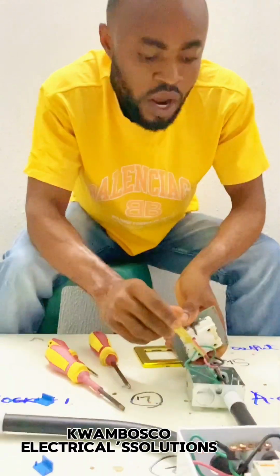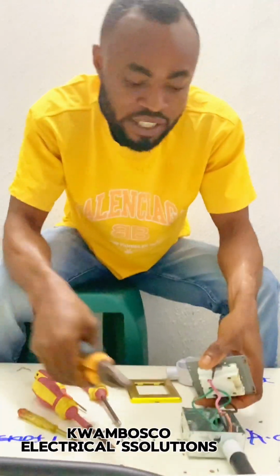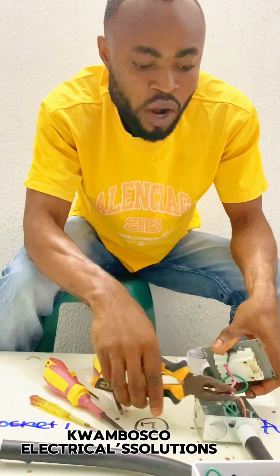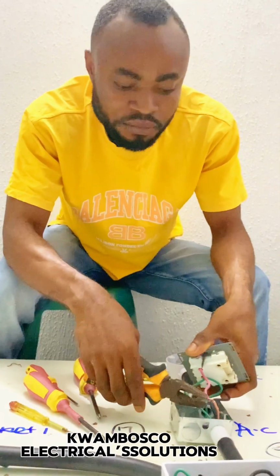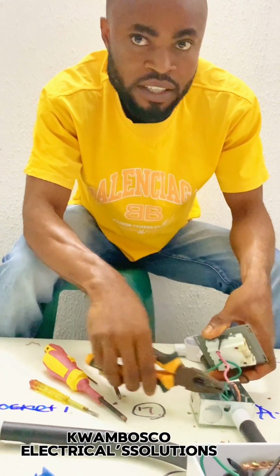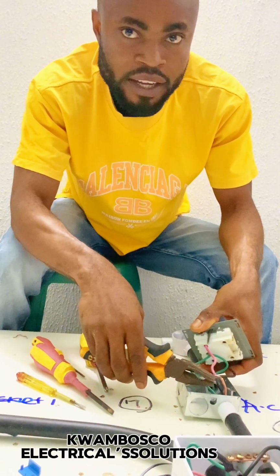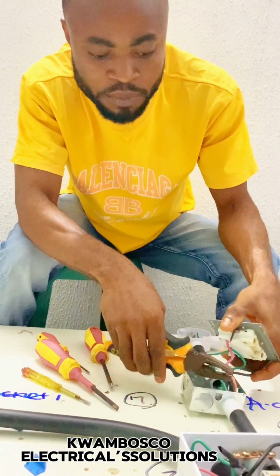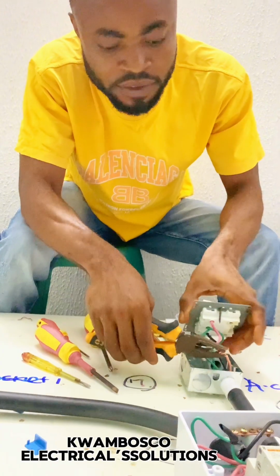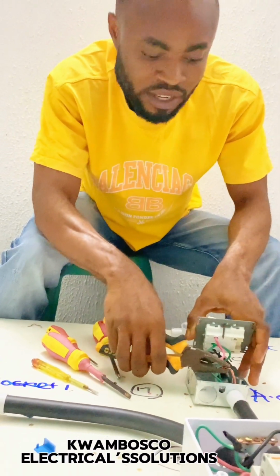Now the reason why you sometimes find this issue is in conduit wiring. It is easily found in conduit wiring, because while you are drawing your wires through the pipes, they may eventually peel their insulators, this rubber that is used to wrap the copper. So after you must have seen it, you use your tape to tape it. You tape it very well. This is one of the easiest ways to find this kind of fault.